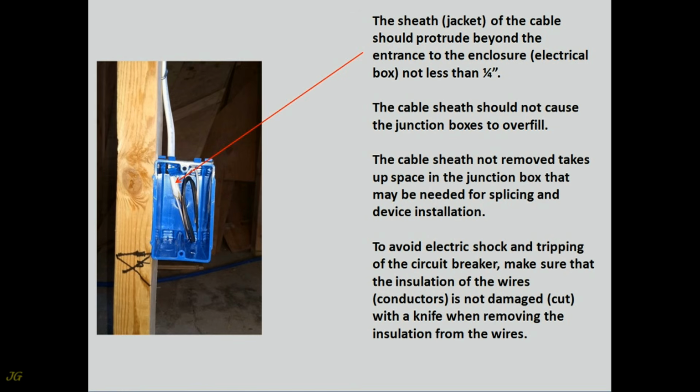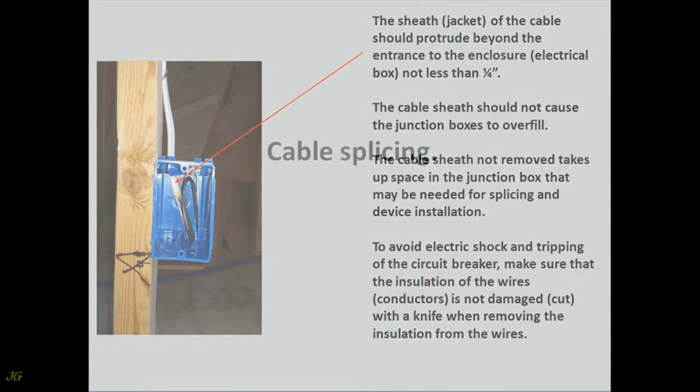To avoid electric shock and tripping of the circuit breaker, make sure that the insulation of the wires, conductors, is not damaged. Cut with a knife when removing the insulation from the wires.